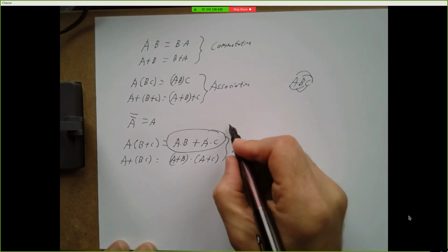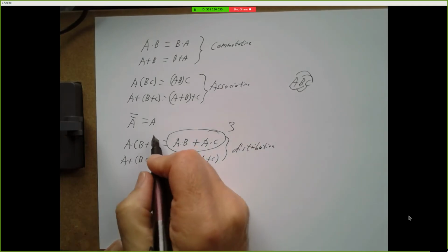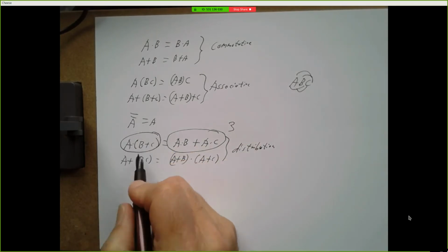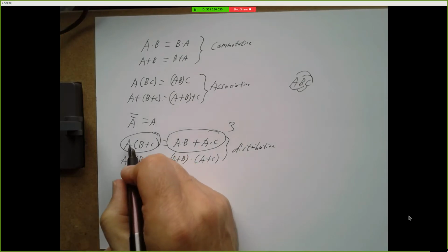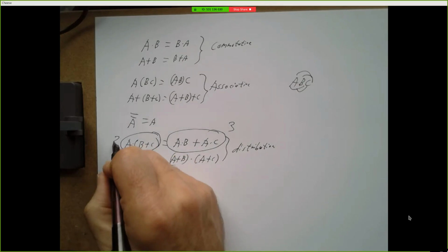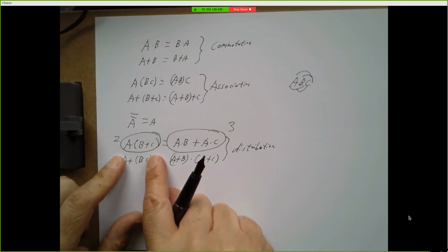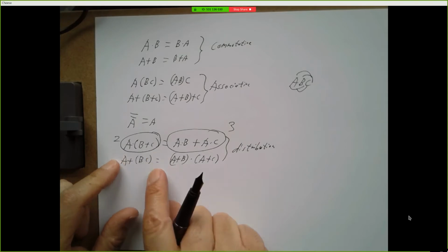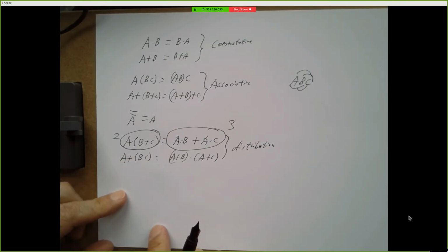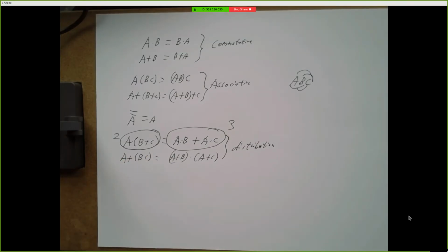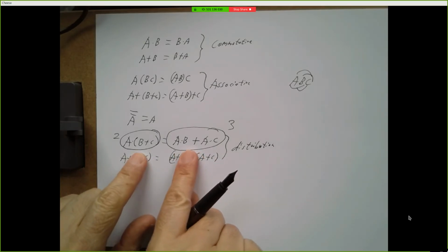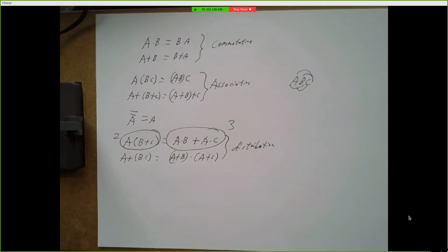That's 3 gates. If we knew that that was equivalent to this, we could build this with only 2 gates, an AND gate and an OR gate. So this is going to be simpler to build. Fewer wires, fewer parts, lower power, fewer places where it can fail, physically smaller size. So understanding these equivalences of these mathematical equations corresponds to equivalences of circuitry.